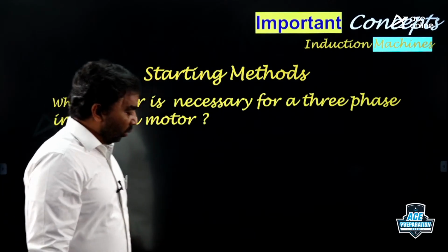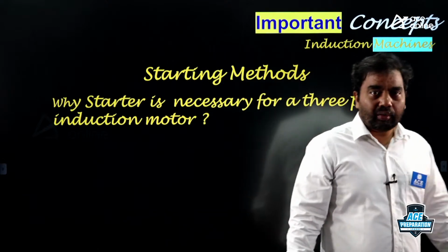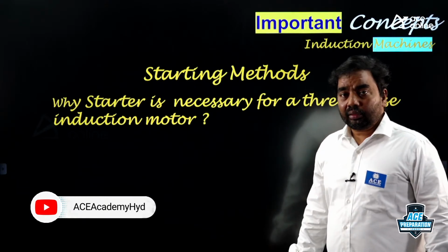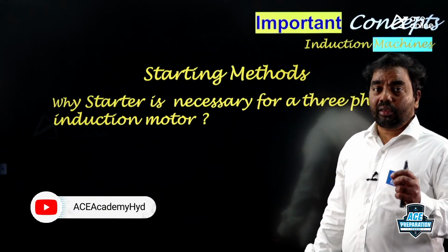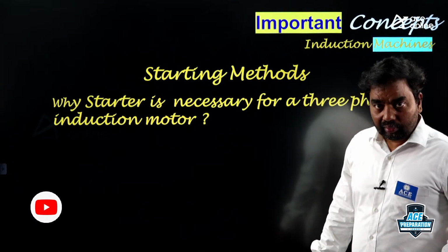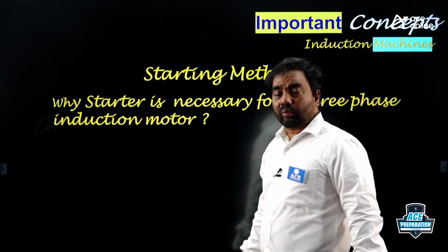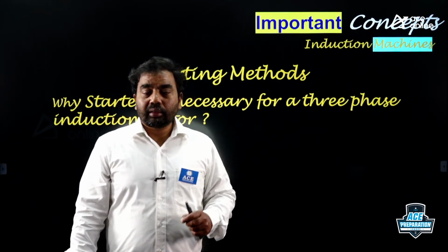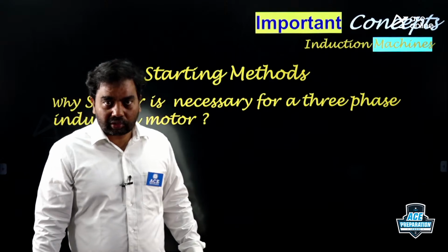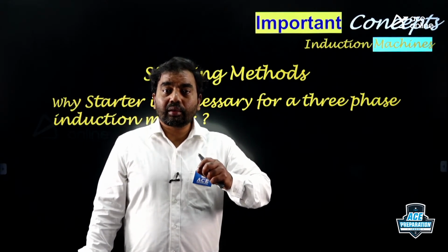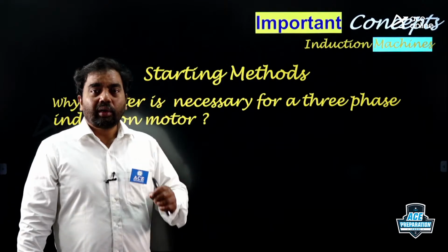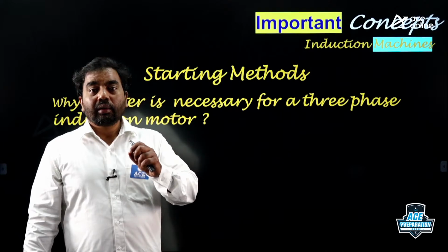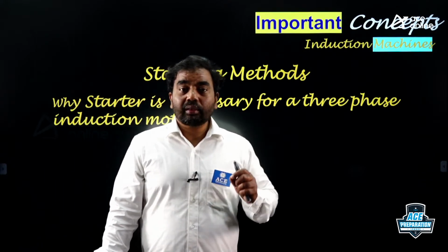First, why are starters necessary for a three-phase induction motor? We are aware that a three-phase induction motor is basically a self-starting motor. But still, a three-phase induction motor needs a starter. As the name says, the purpose of starters for a three-phase induction motor is not for starting the motor, but to limit the high starting currents. Why? Because a three-phase induction motor is a self-starting motor.